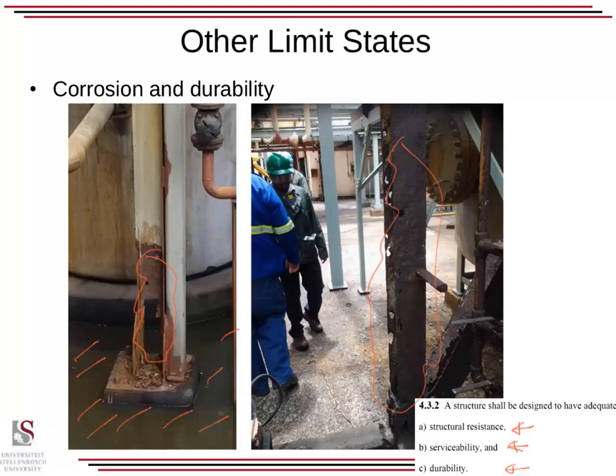If you know your steel is going to be eaten away, you add on quite a few extra millimeters to make it last, and so it will no longer be serviceability or ultimate limit state that governs the design. It would be a durability requirement. Possibly you'll have to put a coating or sacrificial layer on it as well.